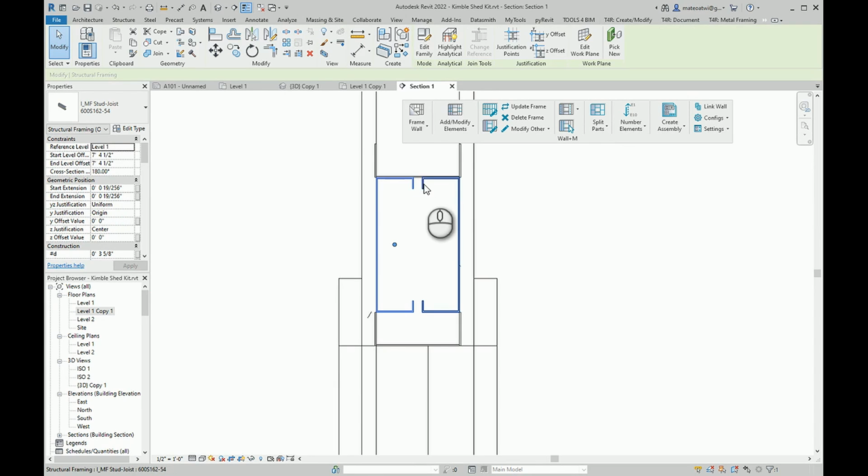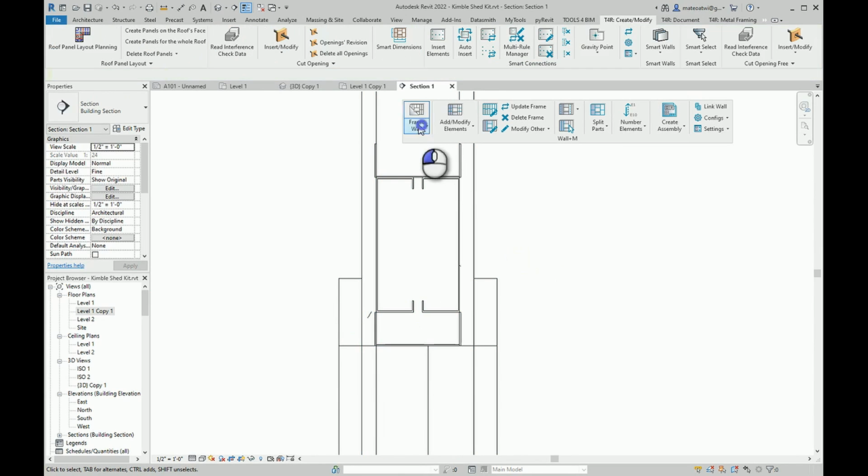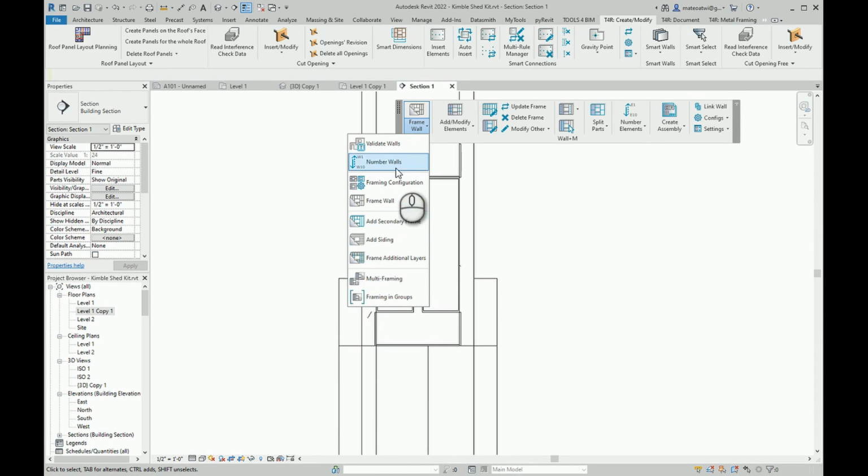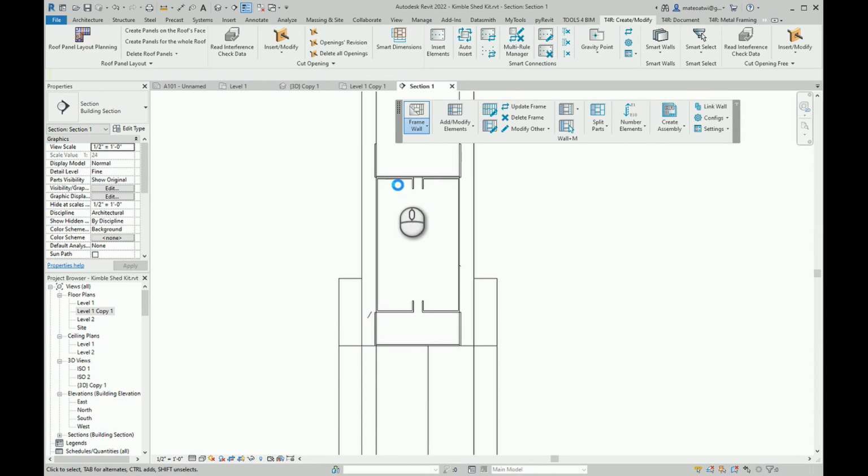And there's our box beam. You can see it's usually two 6-inch studs with a track facing up and a track underneath. In this case, they've kind of botched it and put the track in the wrong spot. So we do have to go fix that.